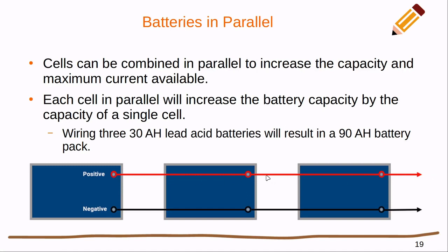Now, when I say can't, I don't mean that you physically can't do it. I mean that these components are going to get too hot and catch fire, which is why electrical fires happen. Okay? There's nothing to prevent you from drawing too much current from it, but ultimately, some of these wires or something are going to get too hot, and the whole thing's going to sizzle down and start to catch fire. So, you have to be more careful about that. Now, if you design the system nicely, you can increase the amount of safe current that you can draw, because in theory each one of these battery packs is only going to be producing some fraction of that current.